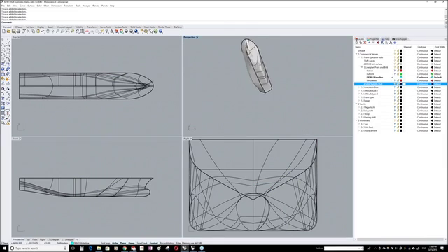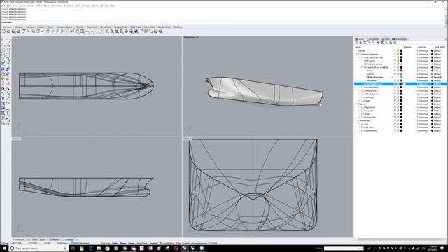And yes, the shape of the midship is clear. I mean, you want a certain bilge radius, you want a certain breadth, and you want a certain depth. That's something you, as designer, want, or you copied from an example ship. And the bulbous bows are now a bit difficult, maybe too much to explain. And yeah, you have to make a decision: do you want a V-shape of ship, or U-shape of ship, or a round of ship? But it's really up to the designer.